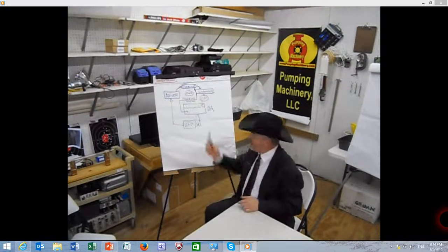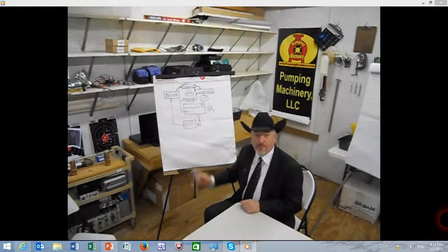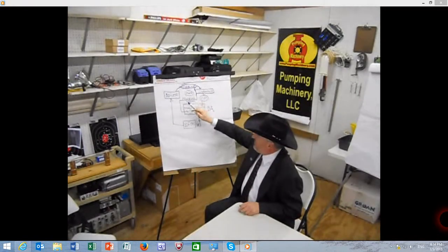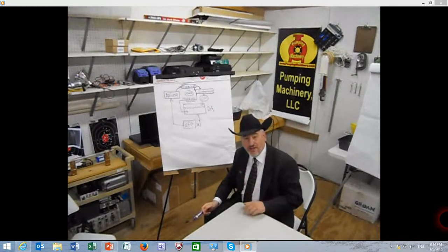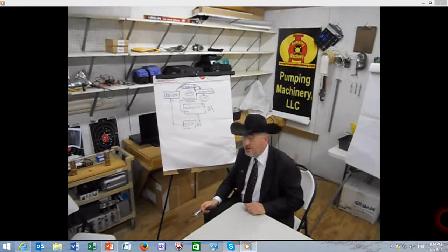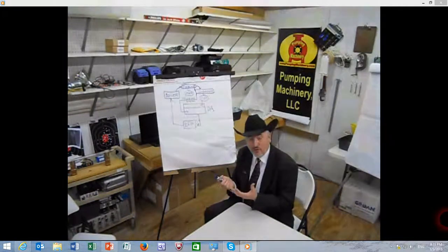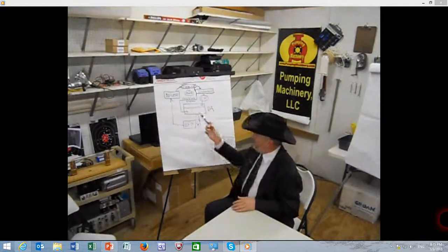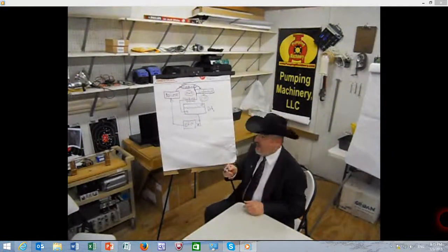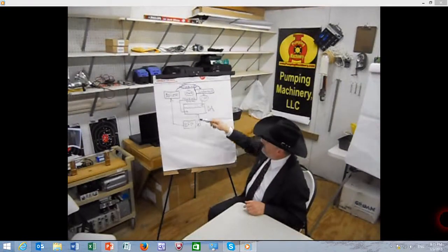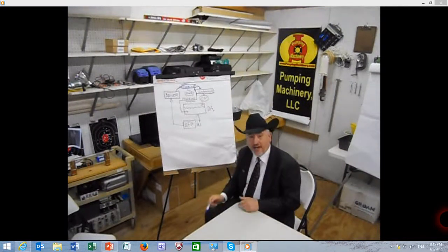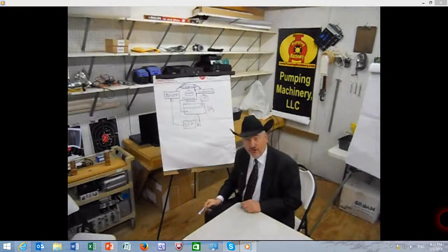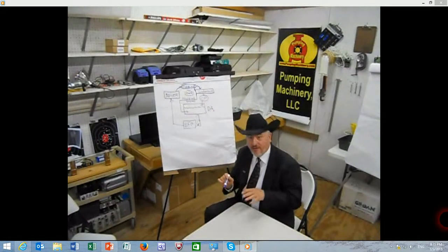And during this process, the Deaerator gets pegging steam, so-called pegging steam, extracted from the turbine, usually the intermediate or low pressure side of the turbine. That steam heats up the water, keeps it in saturation under the pressure, and removes the air. At the same time, condensate that is coming to the DA is on the colder side. So steam is hot, condensate water is cold. Overall, everything is in balance.